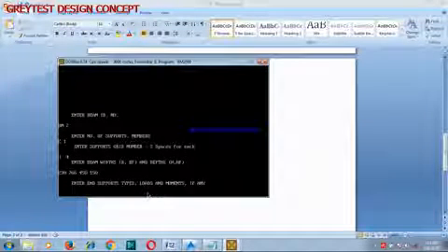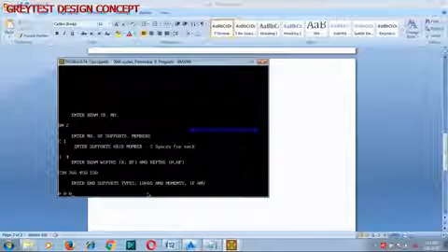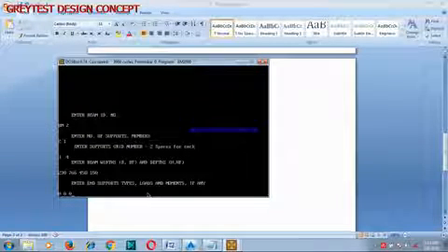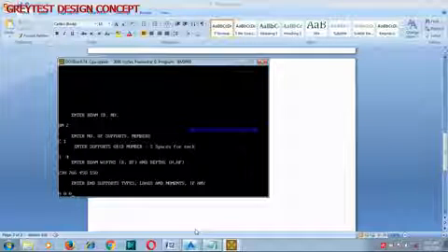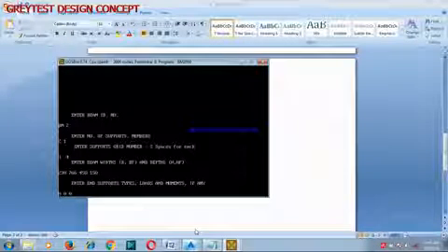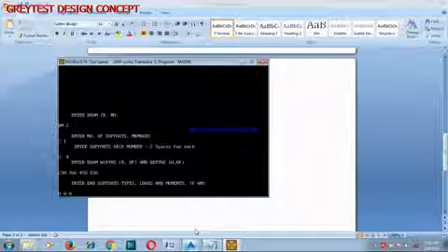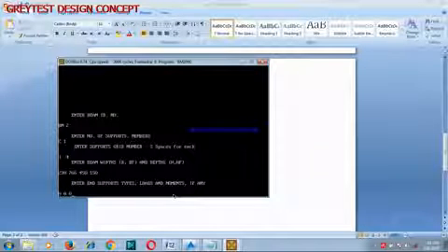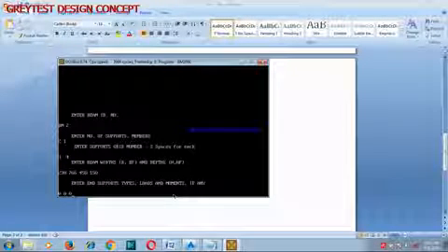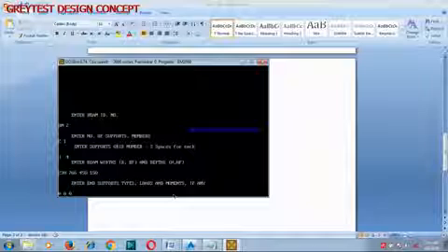Enter end support type 0,0. I believe you remember. Okay, what support? Is it a fixed support? Is it a pin? Is it a cantilever? Those will determine it, as I said earlier on: for fixed or built-in it is actually 1, and for pin, cantilever or free it is actually 0.